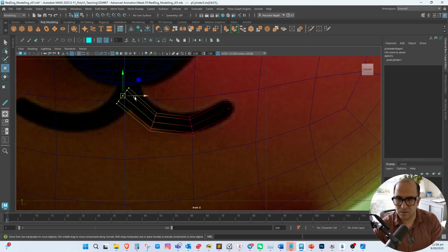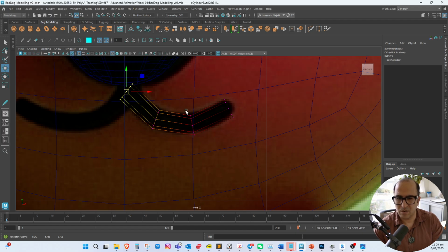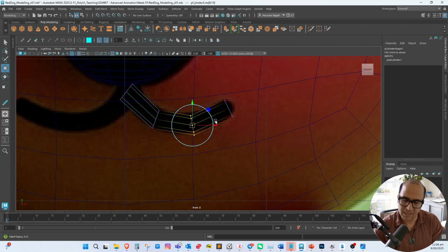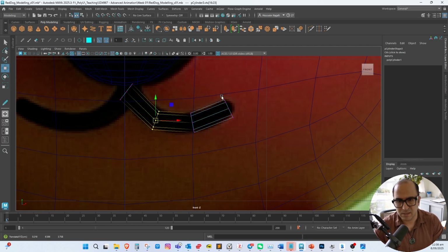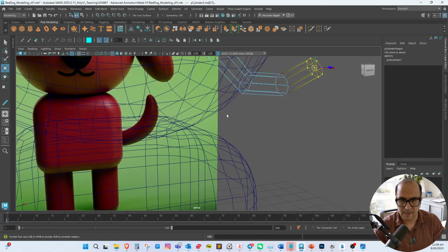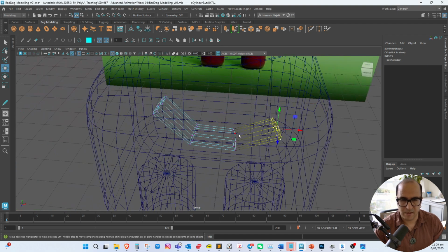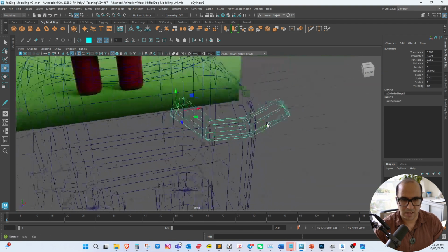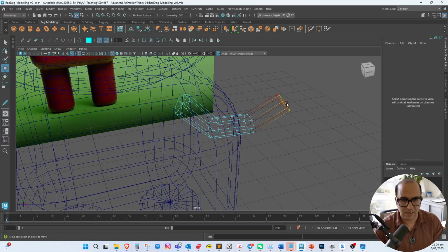You see how interesting soft selection works for you. If I need a smaller range here, I hold B and middle click for a smaller range. So now I have a very nicely positioned set of polygons, and I can select this edge loop.